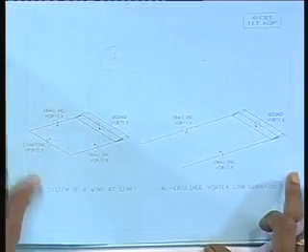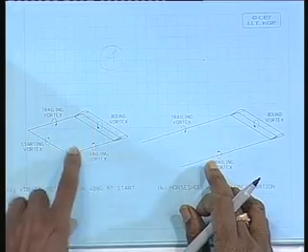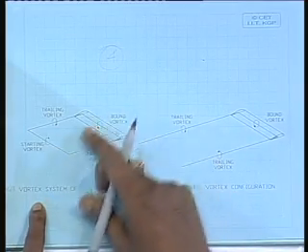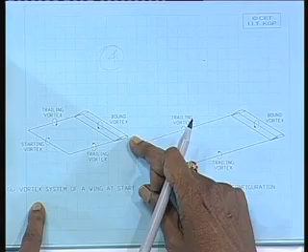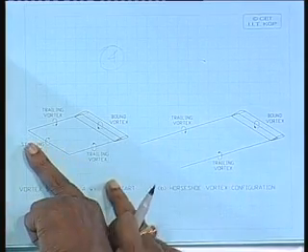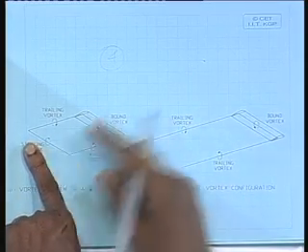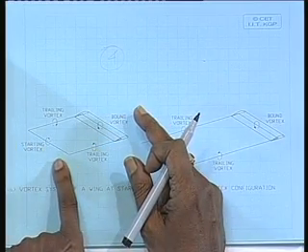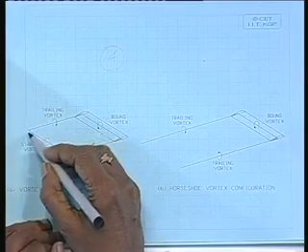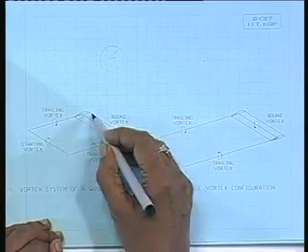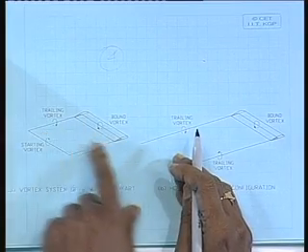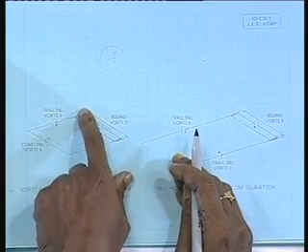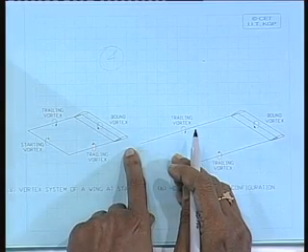So, now if we look at an aerofoil section, you can see that there is a circulation around the section, all along the section, and there is a starting vortex which has been shed from the trailing edge, and since no vortex can start or finish in flow by itself, there must be two vortex lines here coming up which are called trailing vortices, which are shed because of the endings.